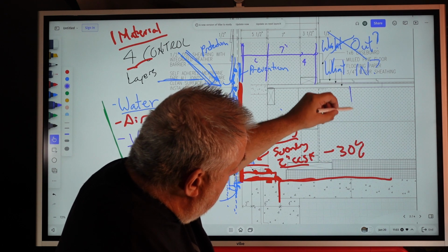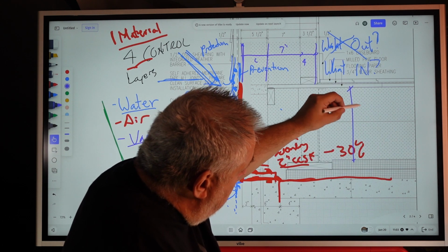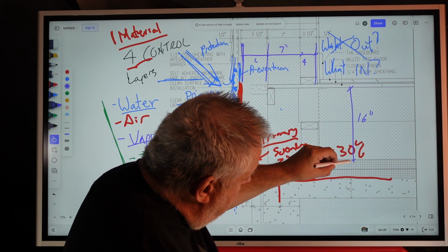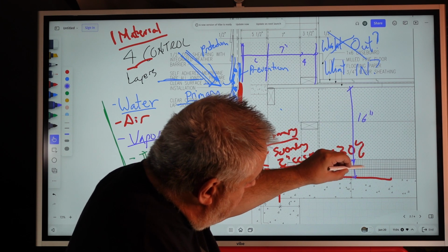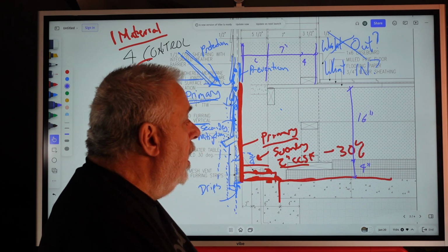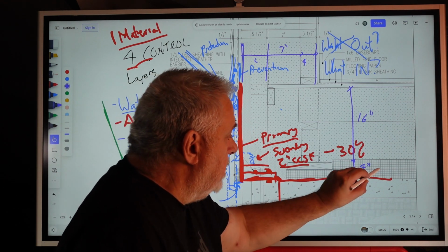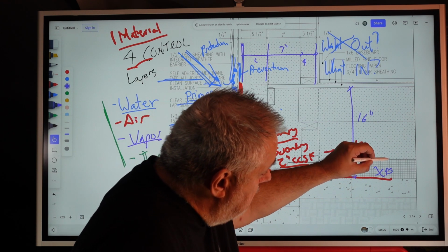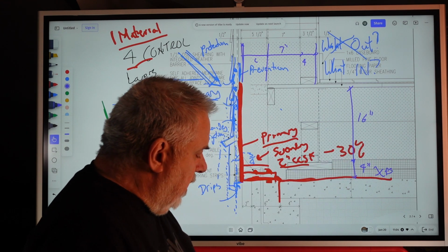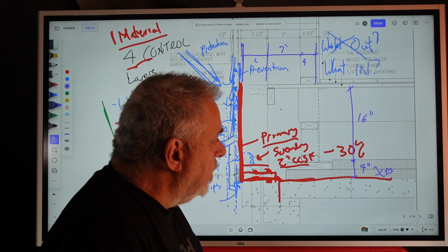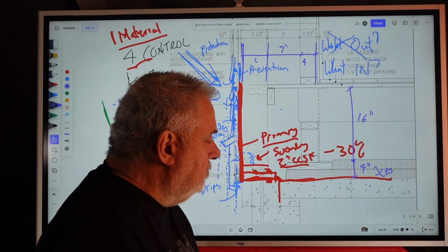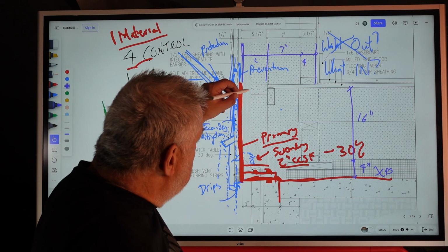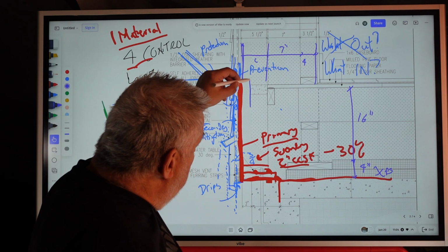And here we have, I think we calculated that at 16 inches and then 4 inches here of XPS. We'll get into the R value when we talk about the thermal controller. But this is semi-permeable, and the closed cell foam here is impermeable.